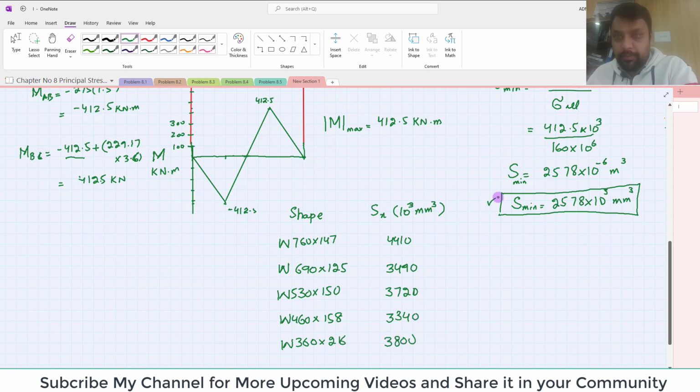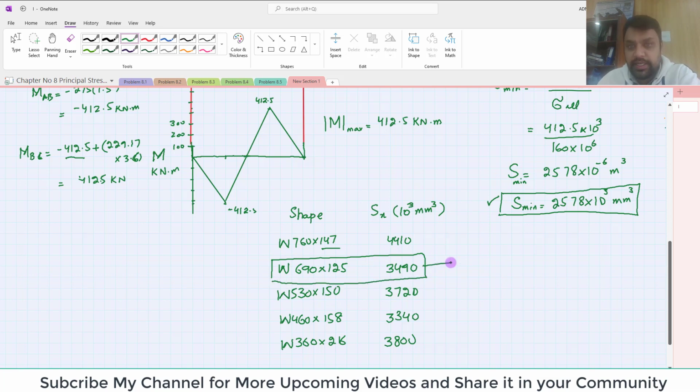So you can see your minimum requirement is 2578, clear, and these are the values which are greater than this, clear. So now you have to select the most economical. You can see the weights are 125, 150, 158, 216 kg per meter. So we will select this beam for the above loading. Select this wide flange, and that will be safe for the above given loading, W690 by 125.